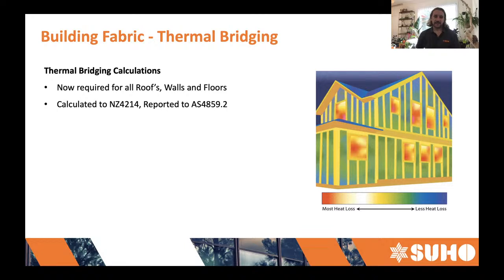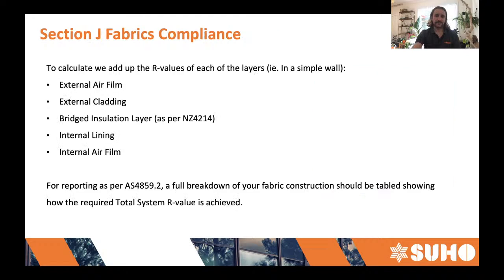So it's typical in a stud wall if you've got insulation batts between it, or if you've got ceiling joists which have got ceiling batts in between them, or if you're intending to put insulation between them, any of those situations, the insulation layer is going to be bridged, and that's going to mean it performs much less effectively, generally, than how it would if it wasn't bridged.